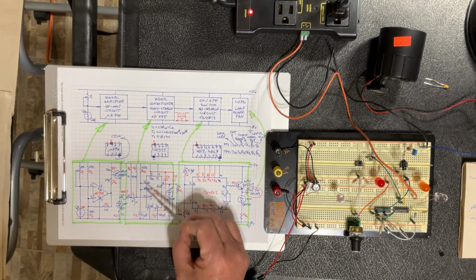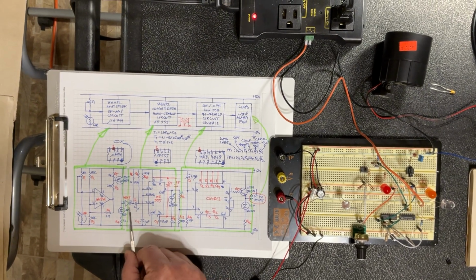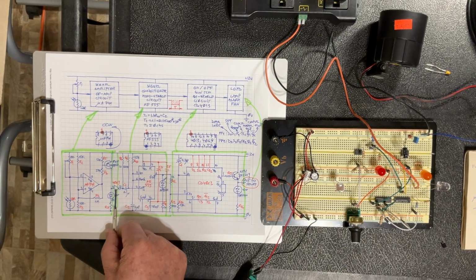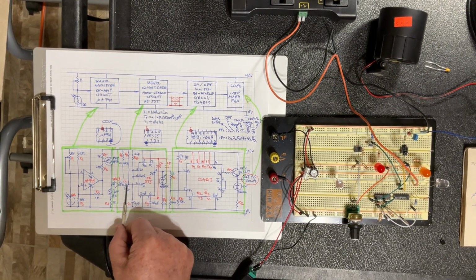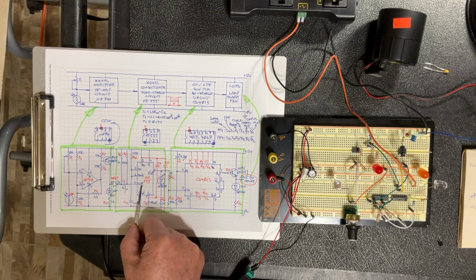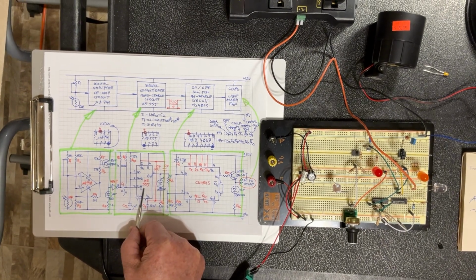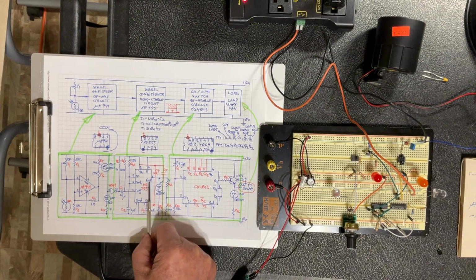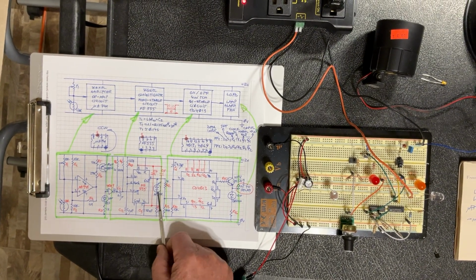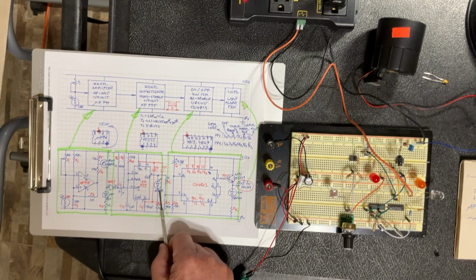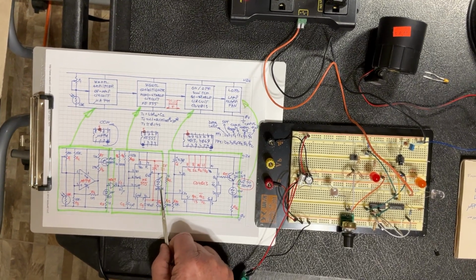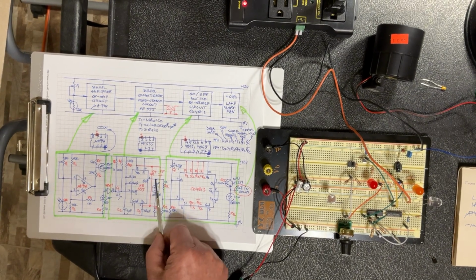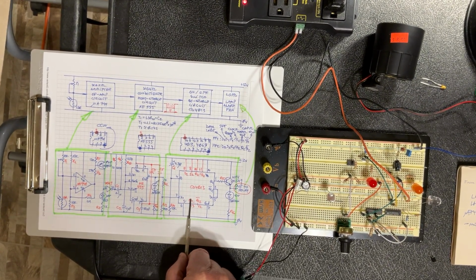So far so good. We trigger that signal by bringing it from the output of the signal amplifier through an inverter and through that capacitor, and it goes on pin 2, which is the triggering input of the 555. And then we get the output, pin 3, of the 555. We monitor here the amber LED, which is about 10 milliamps. And then the signal goes to the next stage.